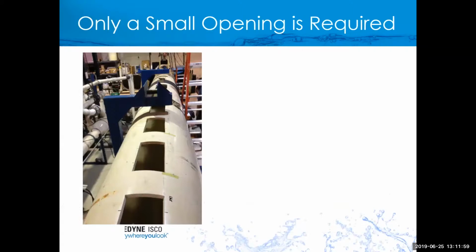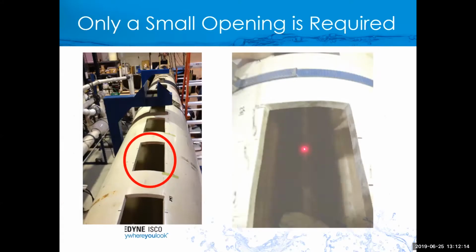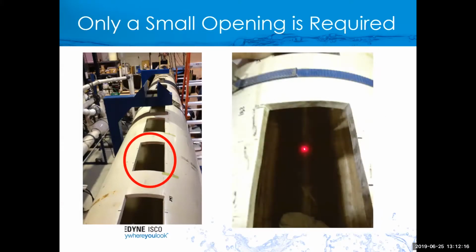Okay, so what's it look like? And people ask me this all the time, how do we install one of these? So I'm going to give you a couple ideas. This is our flow lab. So we just have notches in the top of that PVC pipe, and it doesn't need to be that big, about 3 or 4 inches wide and about 11 inches long, and the laser can read into that. So that's what it looks like there on the flow lab.